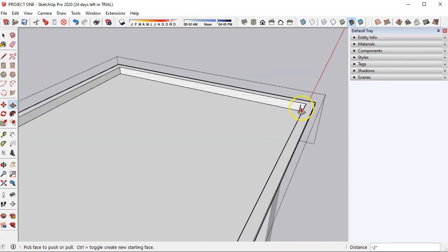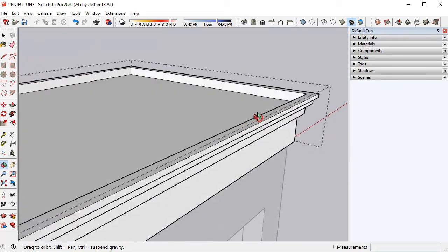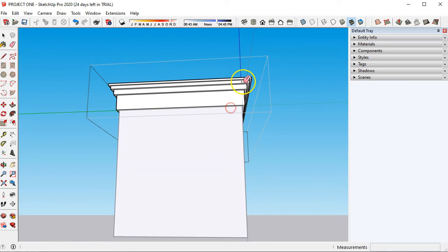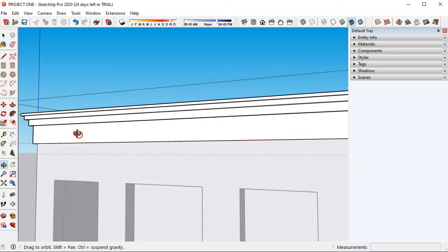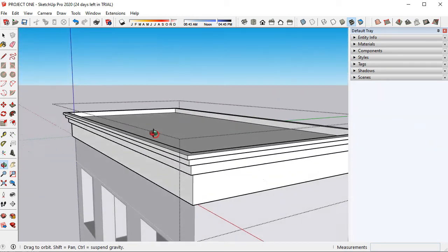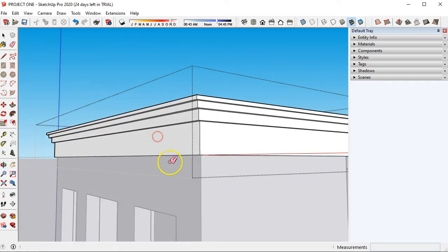And we see a little excess line there that we don't need. Sometimes they appear for no reason, so just delete it. Kind of look around. I like to always look underneath to make sure I don't have any excess lines. The parapet roof is typically higher on the edges than in the center here, or the walls would extend up to this part here.